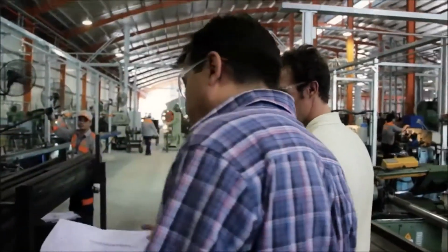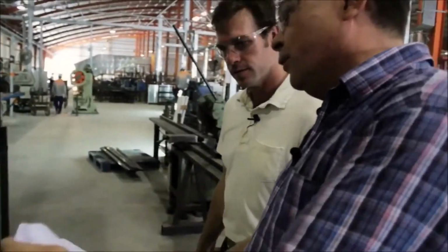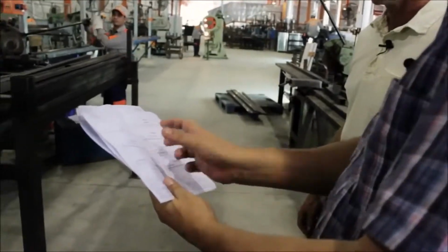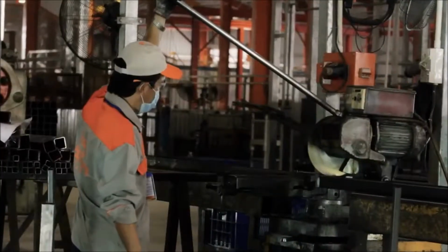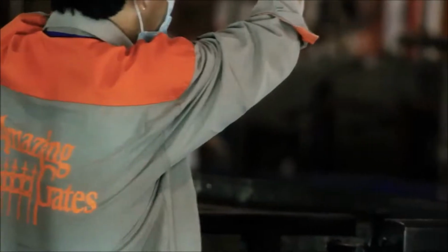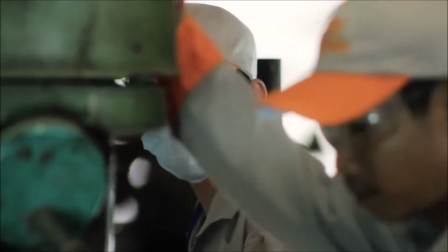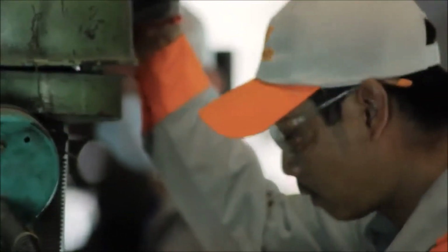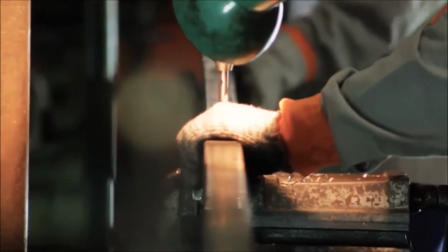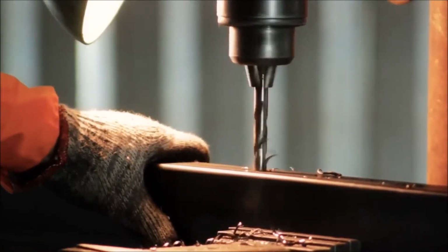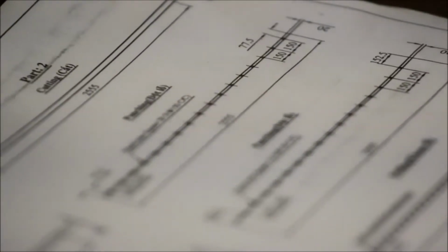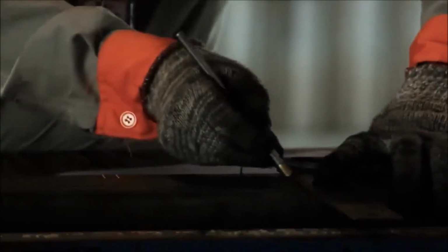So this is where the tubes are cut into each specific size. If you look at the drawing here, you'll see that the first phase is the cutting phase. Okay. So each tube is marked and cut, and then it moves on into the marking stage for the drilling and the punching. As I mentioned before in the design area, this is where each section has the drawings sent to it from production. And as you can see here, after the tube has been cut, it gets marked for the punching and the drilling.